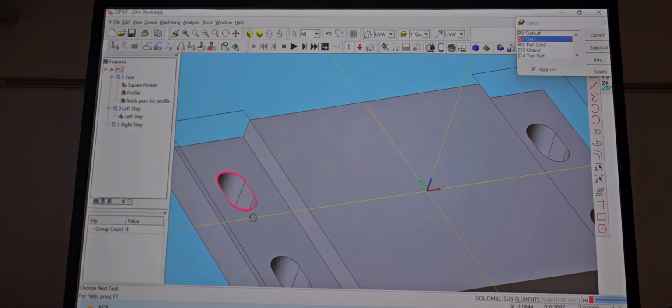Is that where you use T-pocket, or is that for drilling only? It's mostly for drilling, so just perfect circles. On this one though, depending on the size of your end mill, you could probably just do contouring, because it's just gonna go through a slot, right?